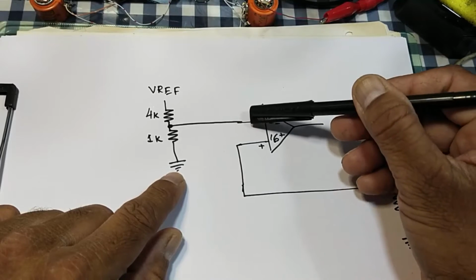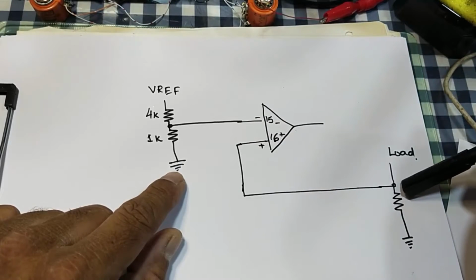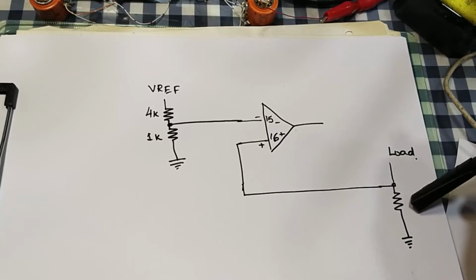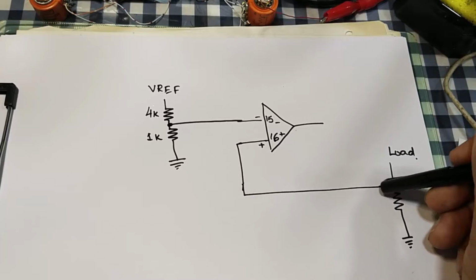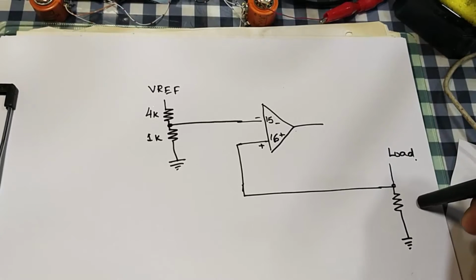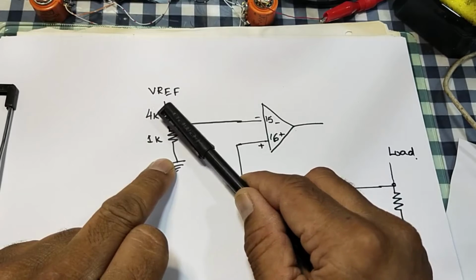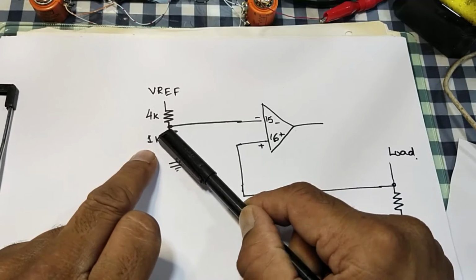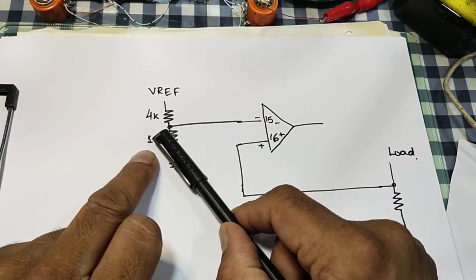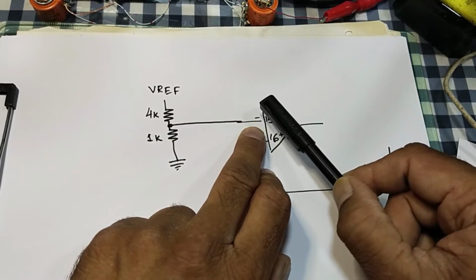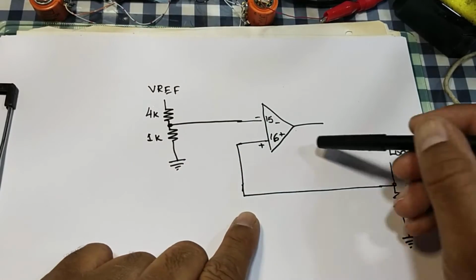If we set this pin at 2.5 volts, in that case we need a very high value resistor at current sense, because here we have to monitor the short circuit current. Similarly, we can use resistor values 4 kilo ohm and 1 kilo ohm, or we can set 8 kilo ohm and 2 kilo ohm to give a 1 volt reference here at pin number 15.